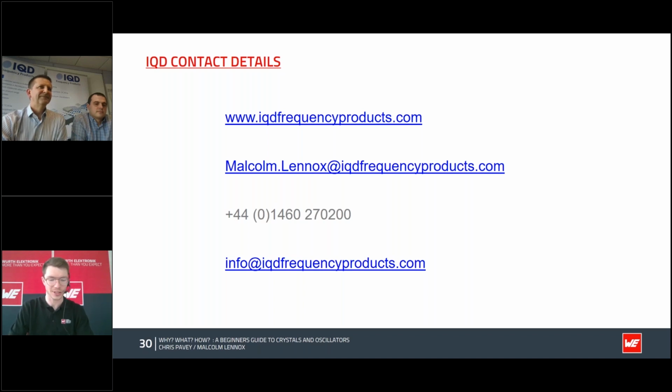First question: what are the advantages in using quartz frequency products over other technologies, for example, MEMS? It's a very good question. Quartz resonators naturally have a very high Q factor when you compare to MEMS and other frequency products like ceramic resonators. Also, quartz crystals tend to have a very good stability when you compare to ceramic resonators and MEMS.